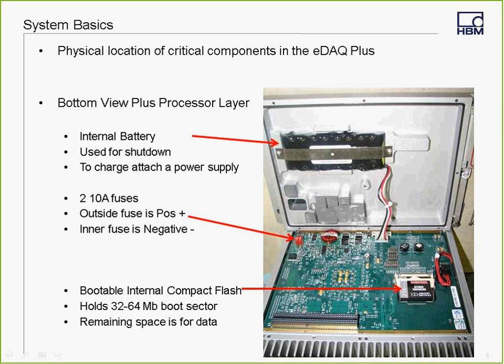There is sometimes confusion as to whether or not the eDAQ can run when power is disconnected. This battery can help power the eDAQ during cold cranking operations, but once power is lost, the battery supplies the necessary power needed for the eDAQ to shut down without losing data or corrupting its firmware. The eDAQ does not need to be on to charge the battery. It only needs to be plugged into a good power source.